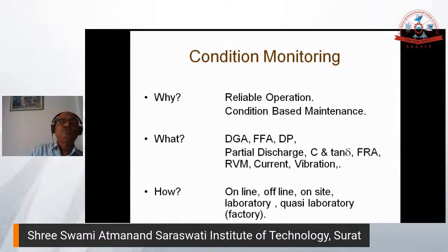Now, why do condition monitoring? For reliable operation, so that there is no unwanted downtime. Condition based maintenance is also normally done by condition monitoring techniques. There are two ways we normally do maintenance. One is time based maintenance, which means without knowing the condition or status of the equipment, you do the maintenance after a few months or a few years.